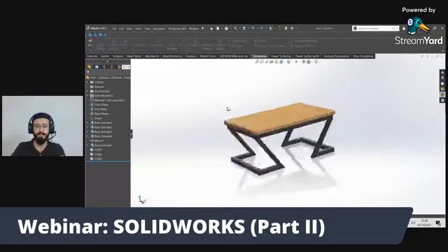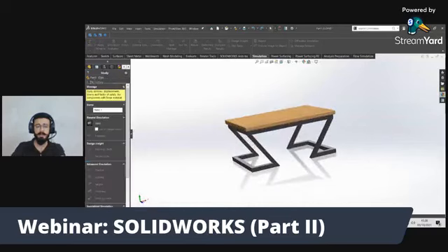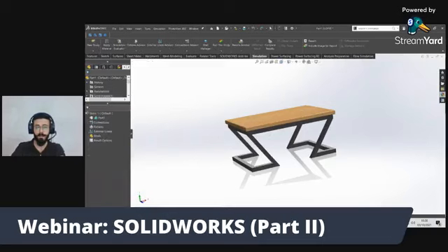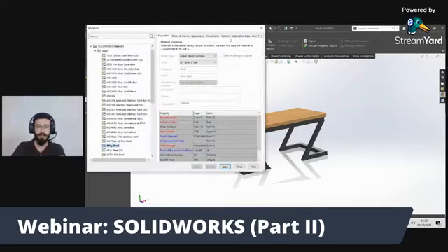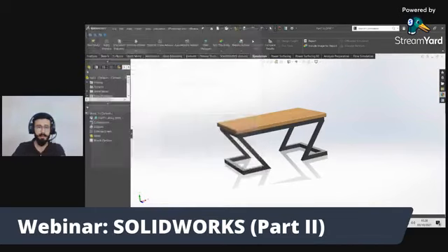Here it's Simulation, and I will select a new simulation. I will use static. Now this is the UI of SolidWorks Simulation. First I will apply materials. Let's select just a random material, we are not making an actual one. Apply. Okay, it's done.